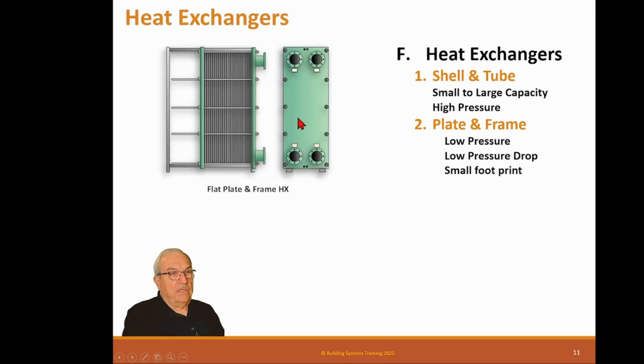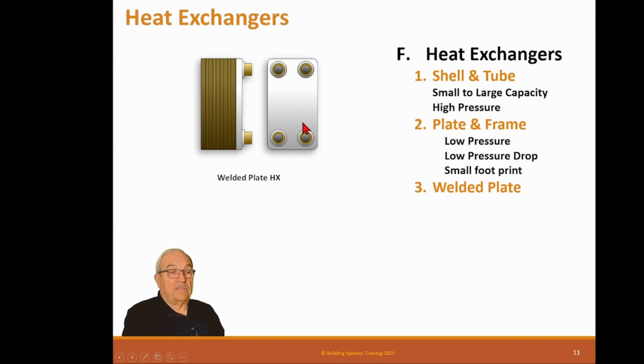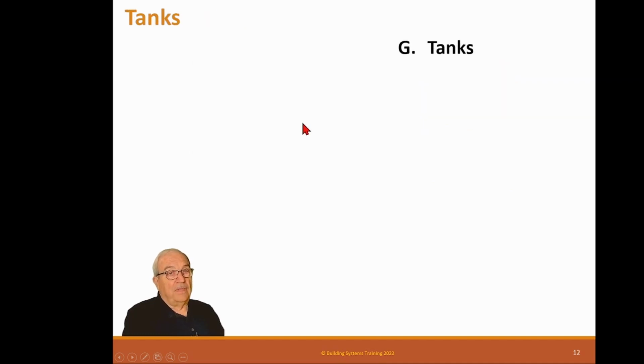Now these heat exchangers here, we'll use these for normal heat exchanger application, but also for chiller economization. So we can put these in a chill water system, and it can take the place of a chiller when we have colder temperatures outside. They have about the same pressure drop as a chiller bundle. So now tanks, a lot of different tanks we use in HVAC.